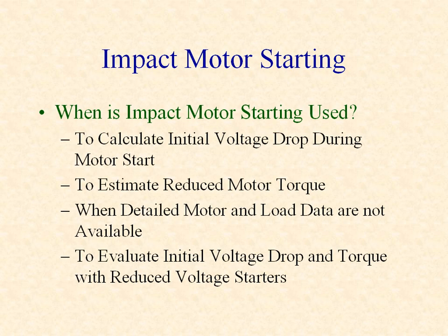Impact motor starting simulation is used to calculate the initial voltage drop when the motor starts. It can be used to estimate the reduced motor torque, knowing that the torque drops by the square of the voltage. For example, 80% of rated voltage results in 64% of rated torque.